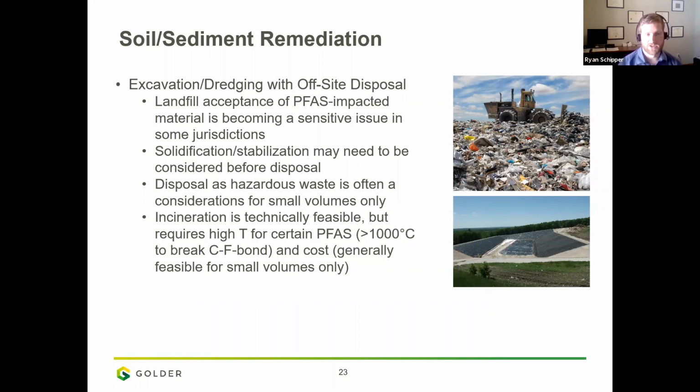You can look at solidification and stabilization, making sure that we bind the PFAS so that a majority of it is not leachable and is bound up within that stabilization binder structure. At Golder, we're working with some companies looking at some of these binders and on some of the research there. Disposal of the soil or sediment as a hazardous waste is often only a consideration for very small volumes.